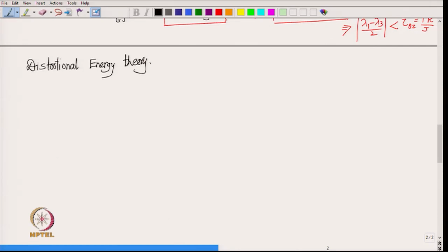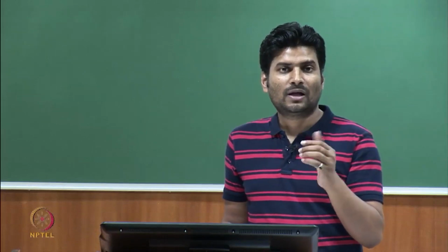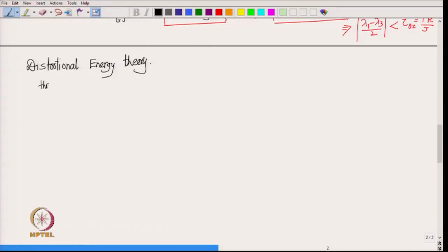Now, suppose that we have an arbitrary body, and then at any point in the body we have an arbitrary state of stress. So, we will have 3 principal stress components. Let us say the 3 principal stress components are sigma 1, sigma 2 and sigma 3. Which of course, you have to find out by solving the eigenvalue problem. They are the eigenvalues of the sigma matrix.